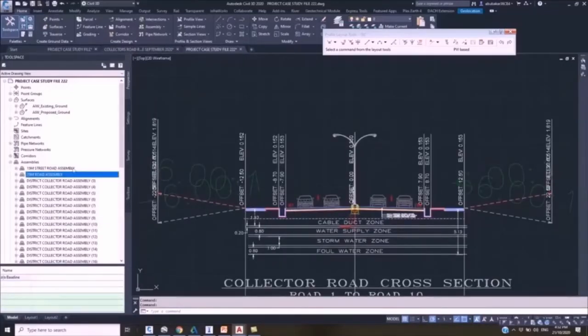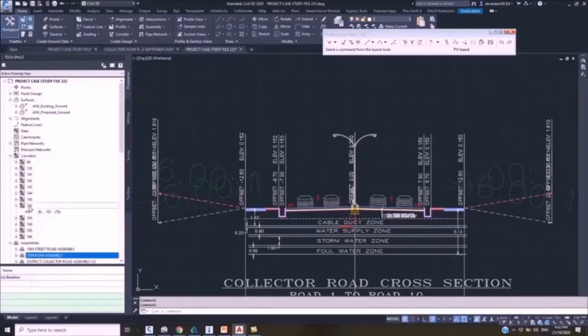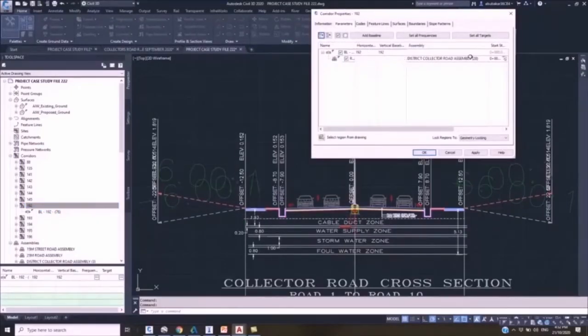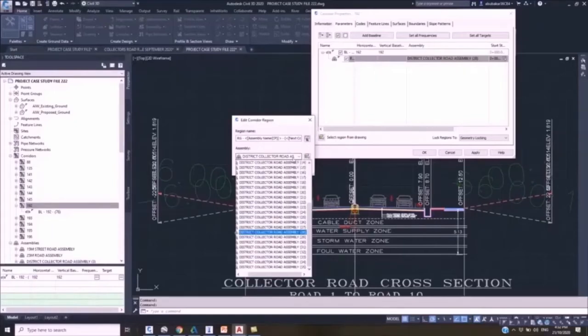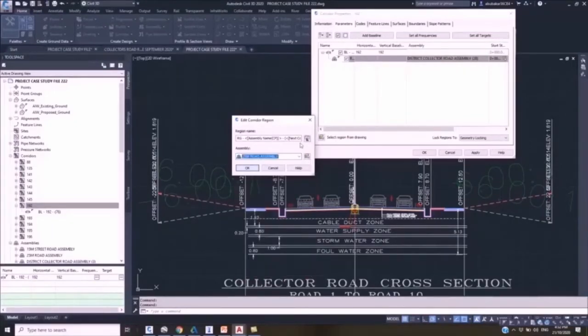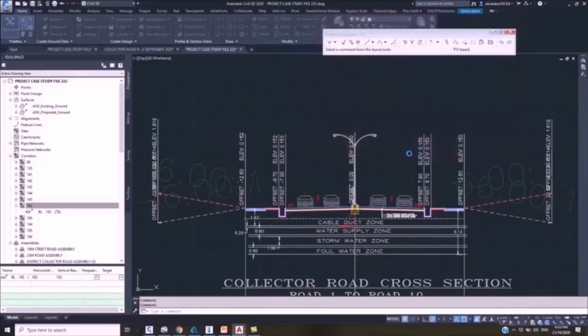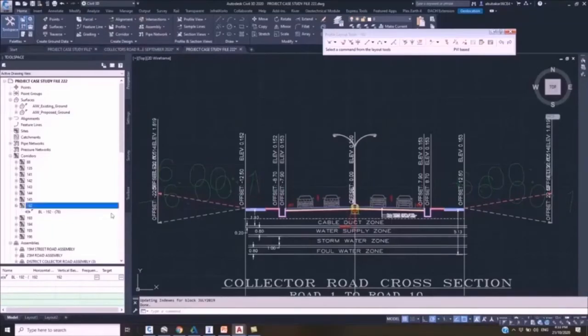So what I will do is go back to the corridor details of 192 and select the properties, the information needed. I will update that information to reflect the conditions of 25 meters as stated, and by default, the corridor will be rebuilt and give the conditions as defined by the client. So I've updated it for this one route. Because of time, I just use this single one to explain. I'll not be able to go through all the 5 roads.